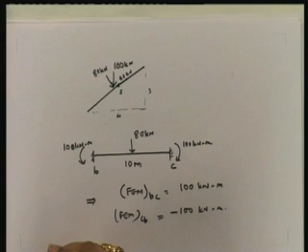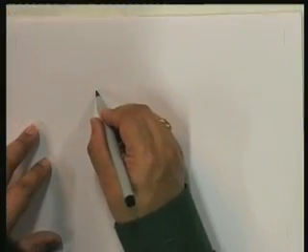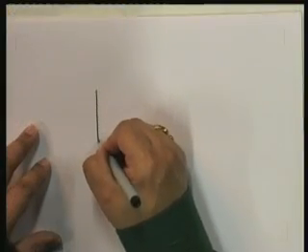Okay? So now what's the next step? We've written the member end deformations, we've found out the fixed end moments. The next step is to find out, for each degree of freedom, the kinematic relationship, the relationship between the member end deformations and the structural degrees of freedom. And for that, how do we do it? Well, kinematics. So therefore, the first step is this.